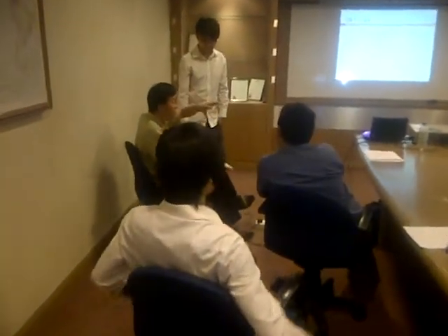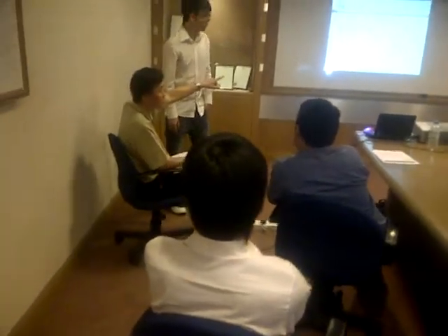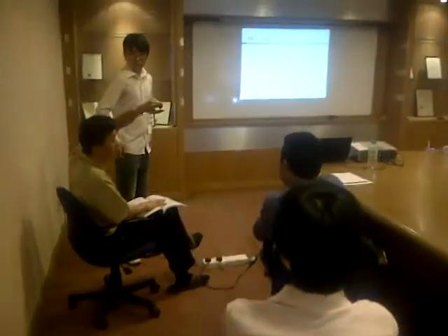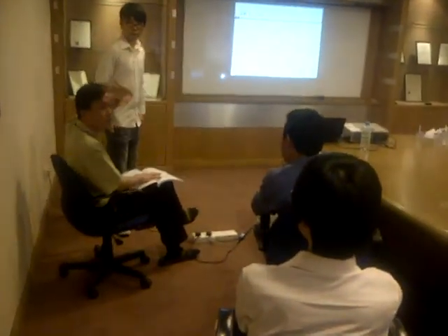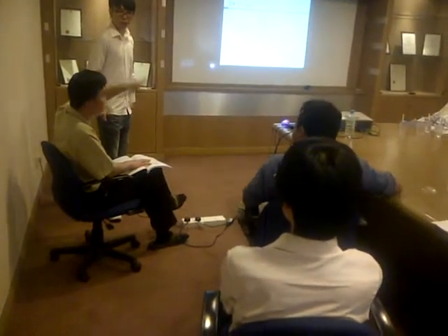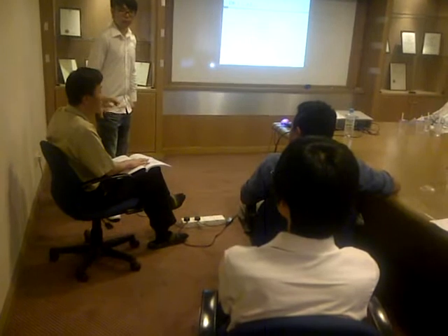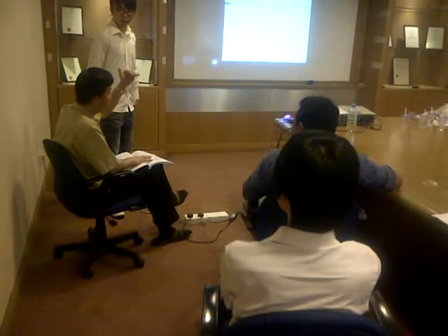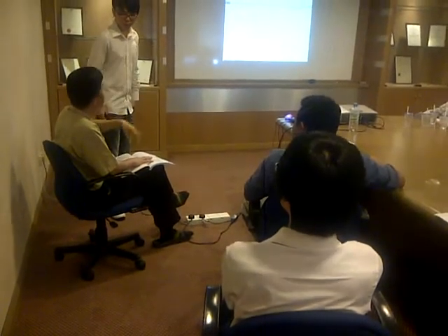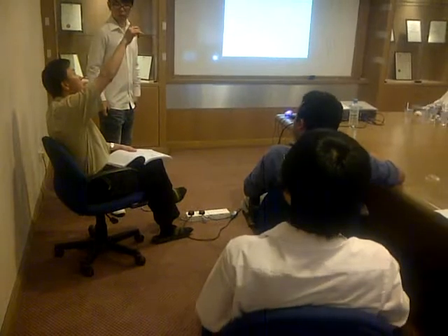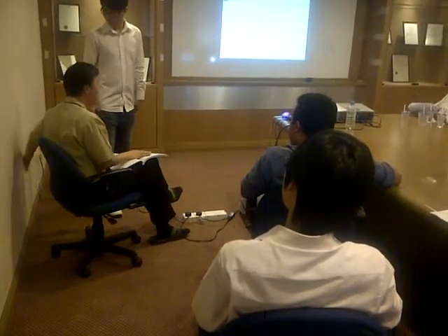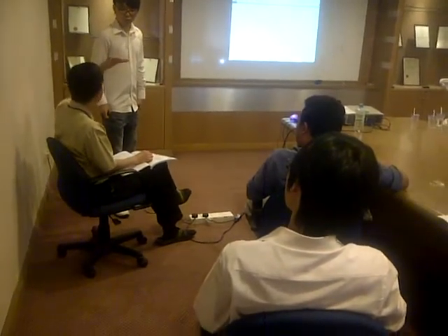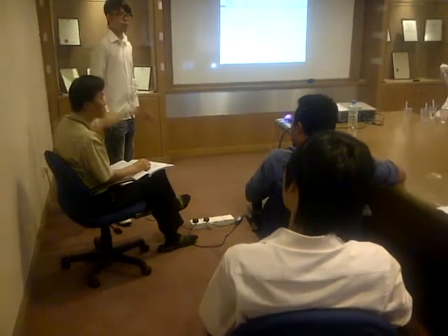If let's say the same size of cable, 6 mm squared, I lay this cable in free air outside the building, free air, which is very much ventilated by air, the current carrying capacity is much better. You can almost reach the specified requirement. But if I put it inside a very cramped area like above the ceiling, or inside the wall, with a lot of cabling inside, the current carrying capacity will significantly drop.